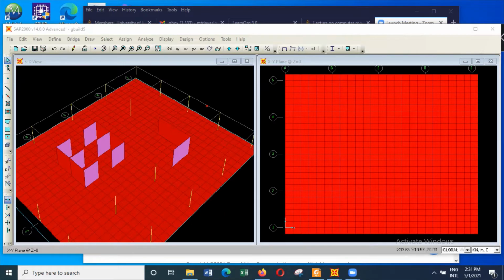And when you multiply this 12,000 kilonewtons per meter cubed by the area represented by each spring, which is 1 meter by 1.25 meters, you'll find that you have to substitute a spring constant K value of 15,000 kilonewtons per meter deformation. So you need a load of 1,500 tons or 15,000 kilonewtons to compress the soil by 1 meter when it is behaving in the elastic region at low loads, because we have maintained the factor of safety low.